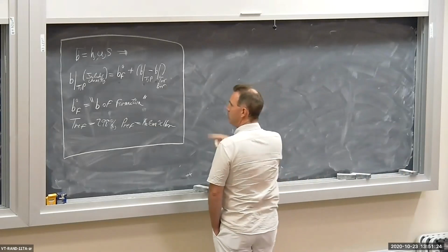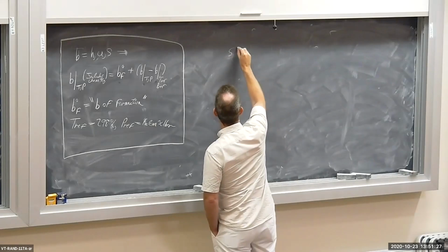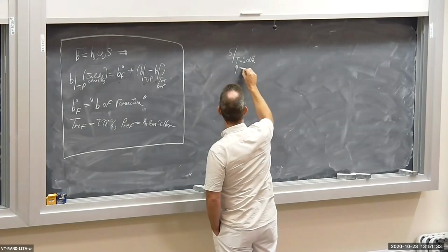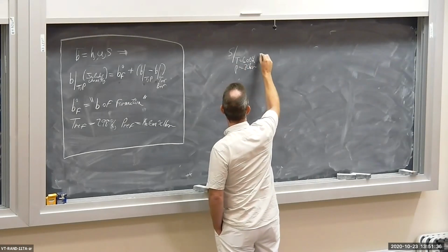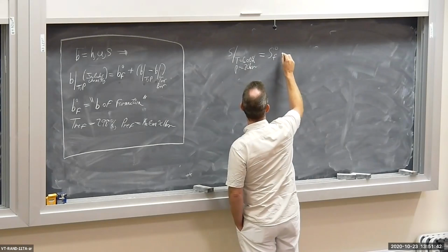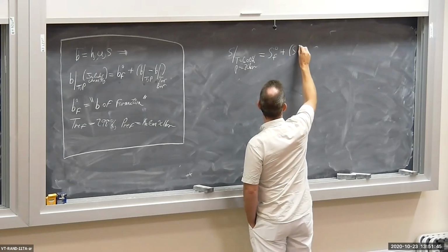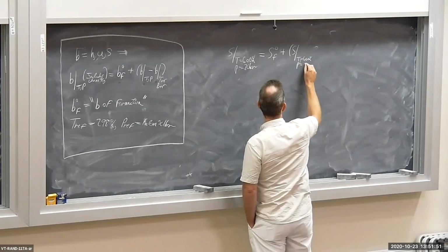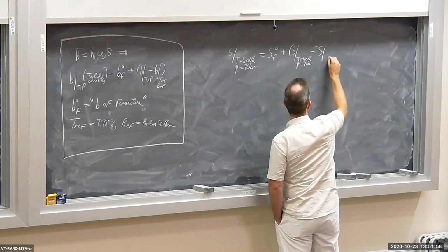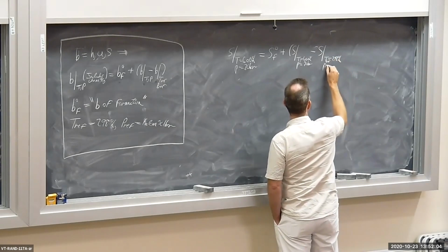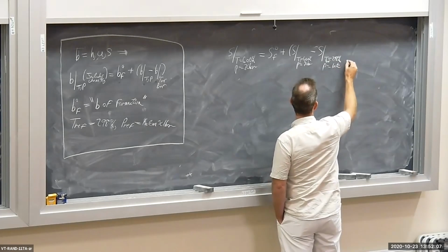Well, using this equation here applied to entropy, so specific entropy at a temperature of 600 degrees Kelvin and a pressure of 20 bar, which will include the effects of chemistry, is equal to S naught sub F plus S evaluated at 600 Kelvin and pressure 20 bar, minus S evaluated at T ref, which is 298 Kelvin and 1 atmosphere, which is approximately 1 bar, okay?